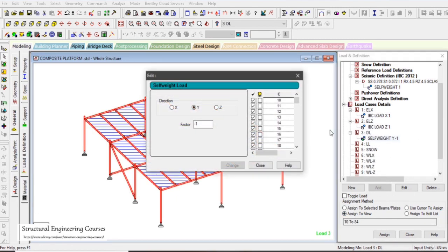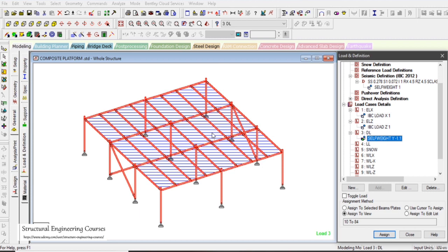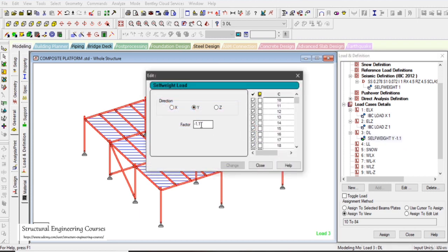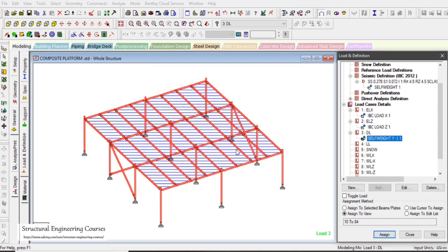And there's this thing that you should understand, that we should always add 10% when we are designing steel structures. 10% is for all the connections weight that shall be installed on the steel structure. So some people take it as 1.05, some people take it as 1.1, but as per my recommendation, always take 10% extra, because connections weight do themselves contribute to the 10% of the total weight of the steel structures.